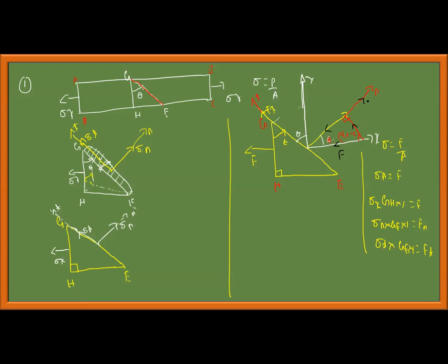But Fn, when I resolve due to load P or due to stress sigma x, you should remember this. When I resolve the force sigma x, for equilibrium there are two forces on this plane, sigma n and sigma t, that will act when you take the section itself. There are two mutually perpendicular stresses, sigma n and sigma t, acting on this plane. Instead of sigma n and sigma t, I have written Fn and Ft. Okay, let's write properly.